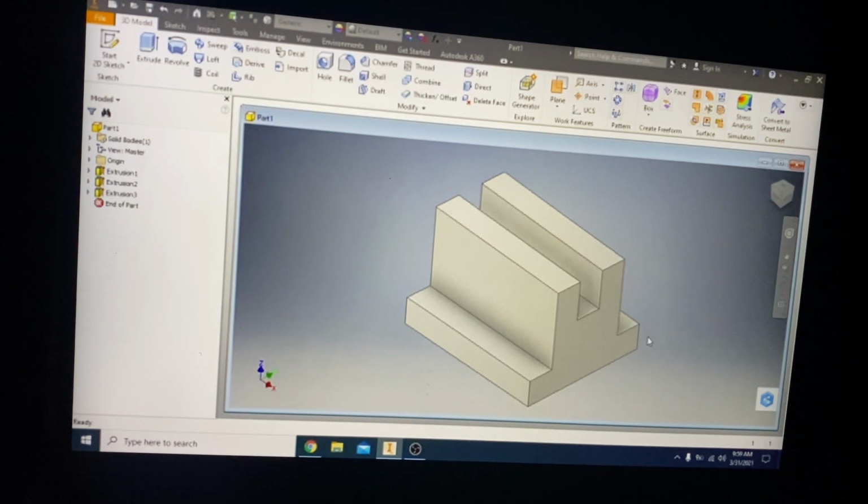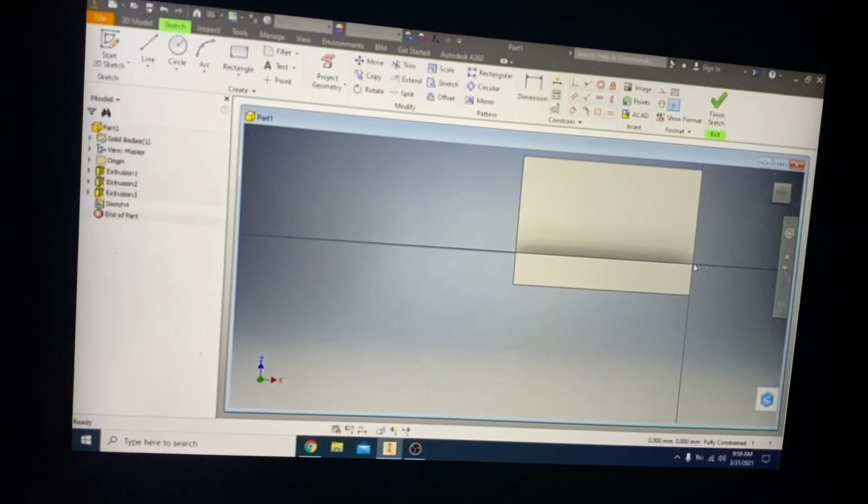Now what is left? The only thing left is the triangle over here. So first thing is I need to go and draw the triangle on this face. So if I need to draw the triangle on this face, I need to go and select start 2D sketch. Okay, click on this line, click over there. Now you see I can draw only on this part of the rectangle. Now you see it is only selecting these lines. If I come down, it will not select it.